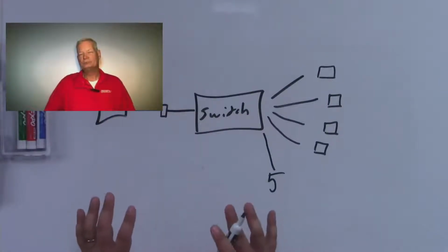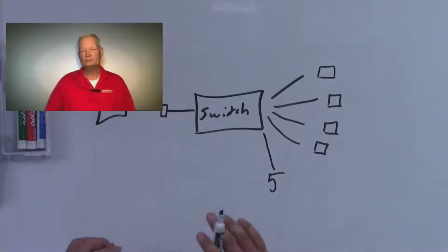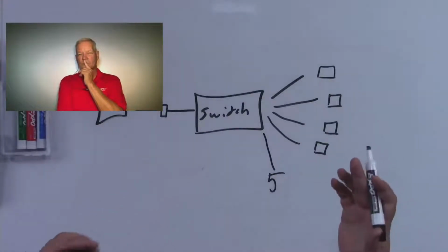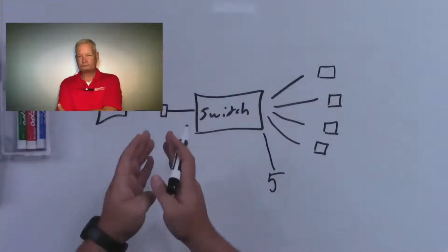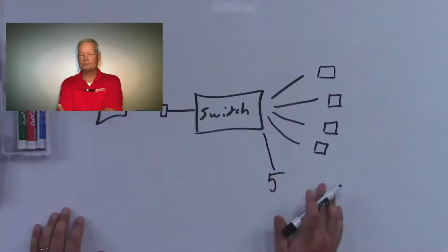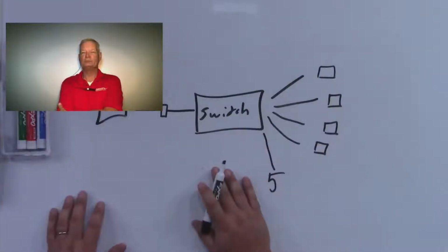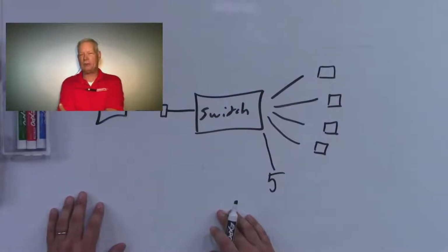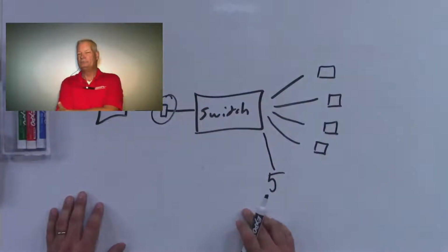Now a lot of this is actually kind of interesting, because when you look at a coupler in place, a lot of times a lower bandwidth like a 720p, a 1080p, absolutely. Even something like a 4K 30 will work perfectly fine with that coupler. But as soon as he tried to do HDR, as soon as he tried to do anything higher than, say, 10.4 or 10 or 12 gig, up to an 18 gig signal, anything higher than 1080p, yeah, exactly. He was running into issues because of that coupler that was in place there.